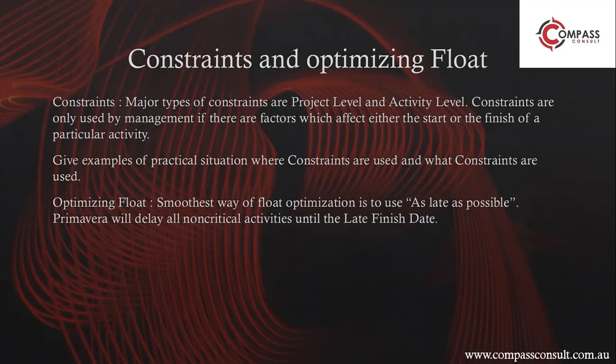You can either make some changes in the logic, in a way that the duration is compromised, I mean the duration is less than what is required between the two constraint dates, or the other option is to reduce the duration physically for activities where you anticipate that this is the duration in which you can actually complete the work. So you can reduce the duration for those. For most people, negative float is a monster, but you can take care of it if you know what you're doing.